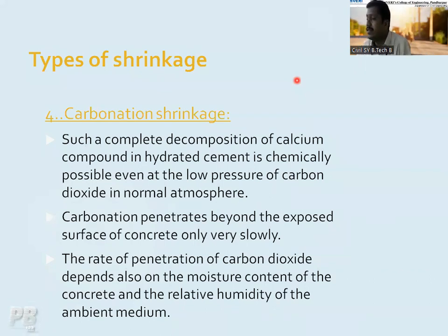Okay, and another case is that due to the variation in the temperature, the sunlight and whatever temperature is there has fully penetrated through the different layers of your subgrade soil of your rigid pavement. Okay, so there is a change in the analysis of the rigid pavements due to these varying temperatures. Due to the varying temperatures, some stresses are induced in the concrete body, and out of that, one stress is your warping stress, and the second one is nothing but the thermal stress.